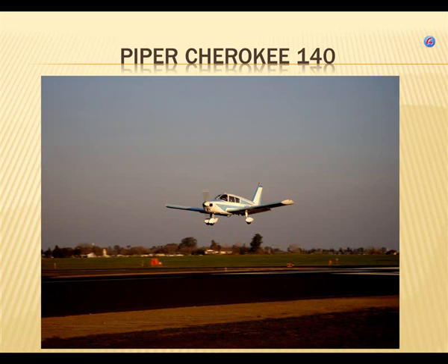There's the 140, a very typical light aircraft, low wing, and it also has what we call a monocoque fuselage. You can get in the back and open up one of the doors, and you can look all the way through the back to the tail, and you'll see mostly skin, but you'll see stringers, that is, pieces of metal that go around on the inside of the fuselage.